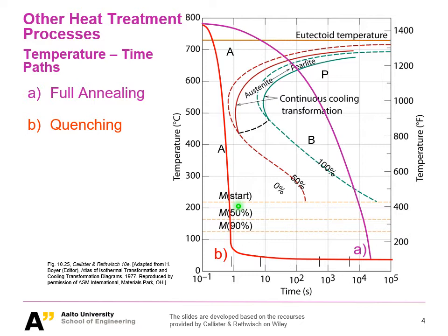If you are lower than this temperature and you avoid diffusion that would form any pearlite or bainite, you will get your martensite. So martensite is obtained through a diffusionless transformation. It is shear-based. Basically, the material is a single phase, a single BCT phase, as you still remember.